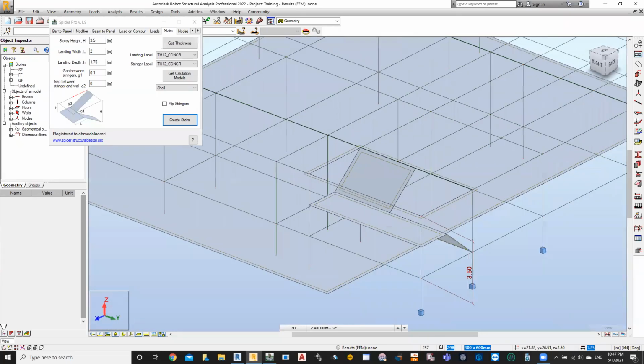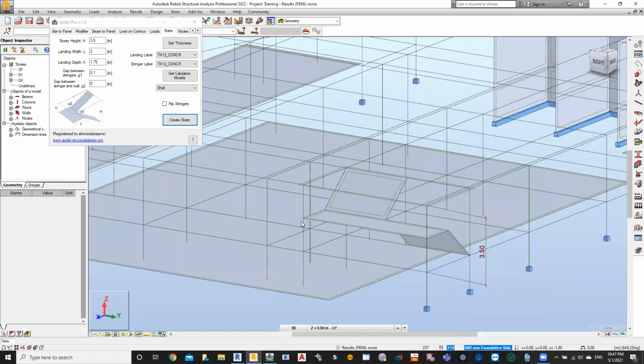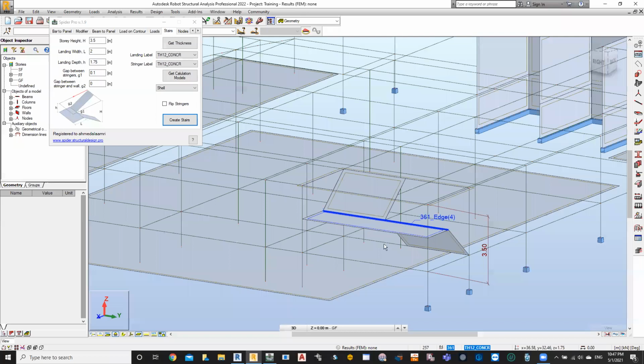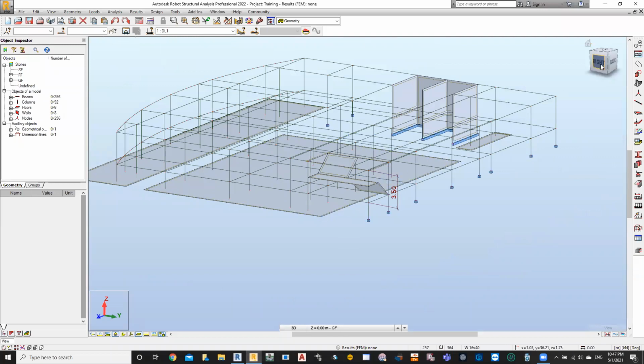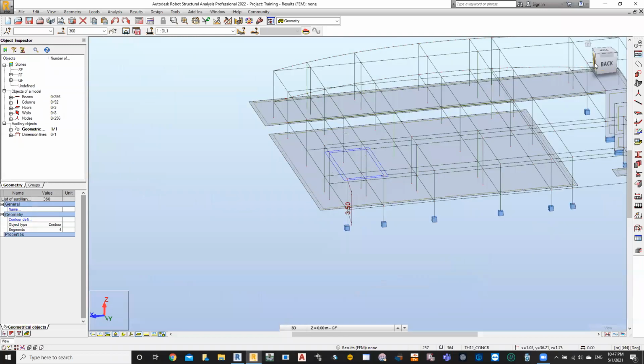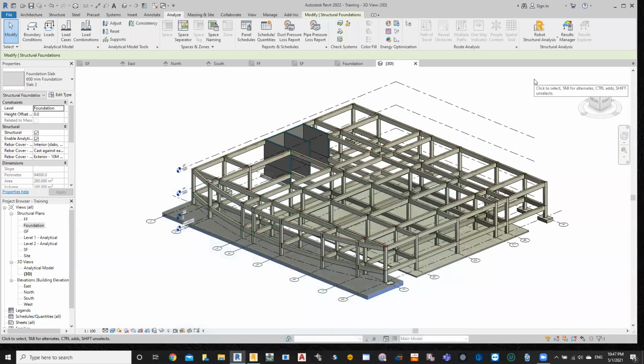You can keep it in the horizontal direction or the vertical direction. Now, of course, here you need to supply another beam because this slab has not been carried by anything. So leave the stair. We'll come to it later, but for the meantime, you need to know how to draw the basic things in your Revit.